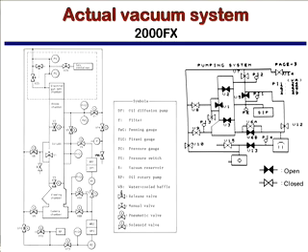And so it's helpful to figure out, okay, here's the viewing chamber. What things can pump on the viewing chamber? Well, what we can see is that the roughing pump, if valve 10 is open and valve 9 is open, will pump on the viewing chamber. Okay? Also, if valve 13 is open and my diffusion pump is on, and either V6A or V6B is open, that will pump on the viewing chamber.